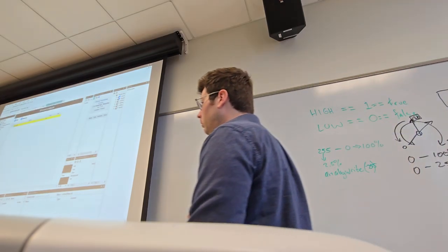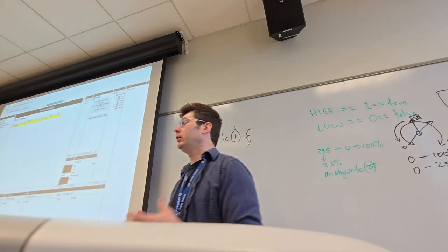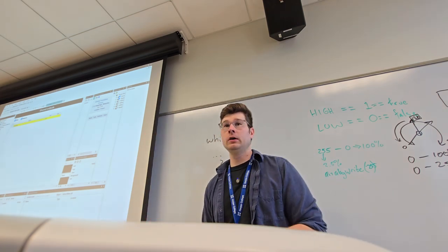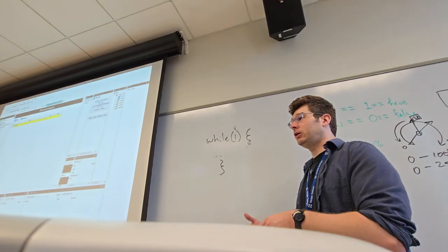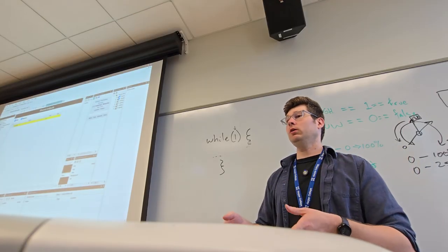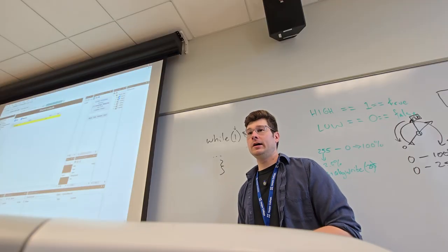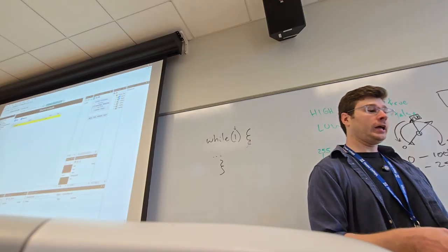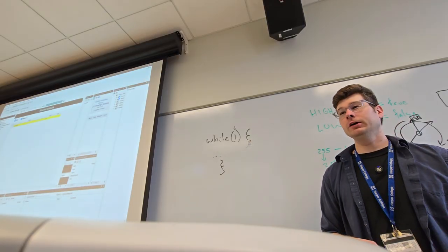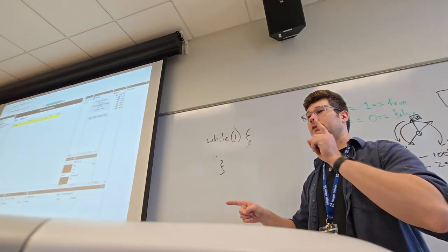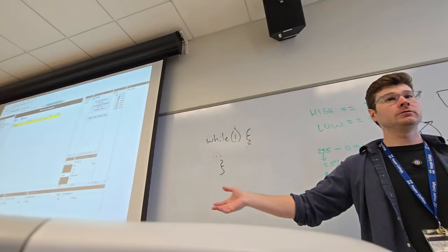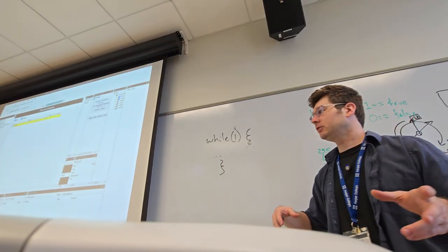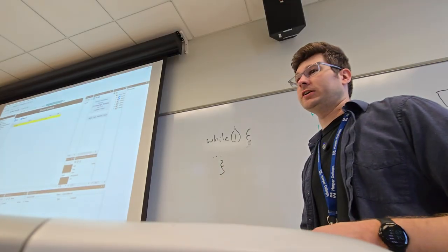Theoretically, by changing the variables in here and creating a simple ladder logic program that pays attention to those variables and changes outputs accordingly. For example, it looks at a single bool that we make, and we have an Arduino program that changes that bool to be 1 or 0. On the PLC side, we have a dedicated ladder logic program that has that input tied to that output, so if it's set to 1, then our relay turns on and is set to high. If it's set to 0, then our relay turns off because it's set to low.